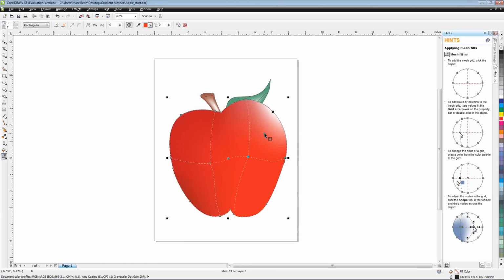I'll click a point on the apple that I want to add an intersection, and then up here I will say Add Intersection. So that's another way. The third way is to actually double-click anywhere in the apple that you want to add an intersection. So I'll add one about there, and that also adds an intersection. Doing it these first ways, though, of course, adds both a horizontal and a vertical line. And double-clicking again will delete the intersections. So double-click it again, and it deletes it.